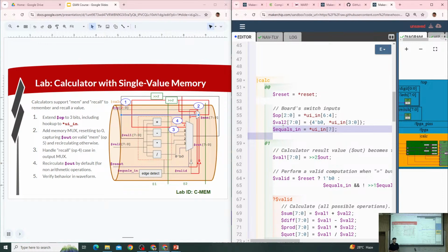To me, asynchronous reset just causes mischief. It's not a question of synthesis, it's a question of methodology and how you code your logic. An asynchronous signal is going to propagate through the logic however it does and arrive where it arrives however it does.